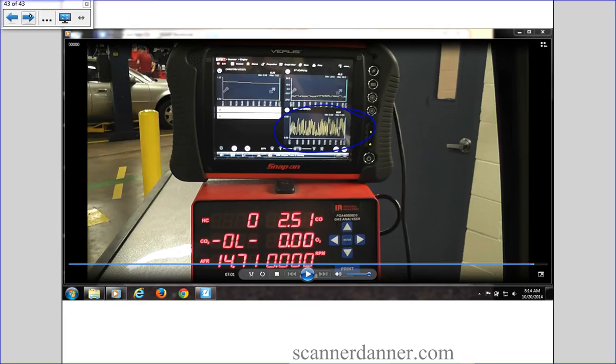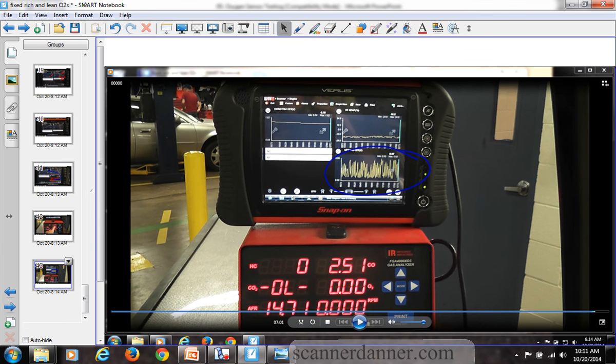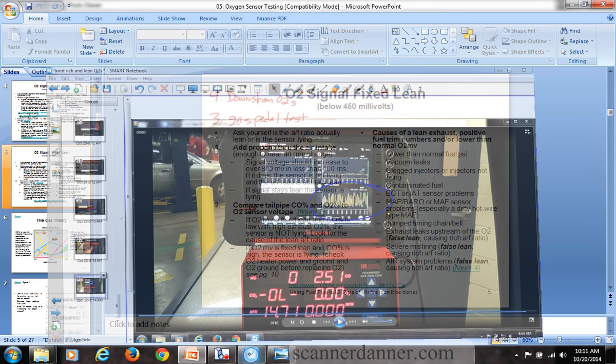I don't like to be, but if you can't duplicate the fault, what's your next step? What's the most logical cause of a slow response fault code that you can't recreate? It's about O2, so you change it. You know, don't forget about vacuum or false lean conditions. Our test will not be tomorrow. I need one more day with you guys on this subject.